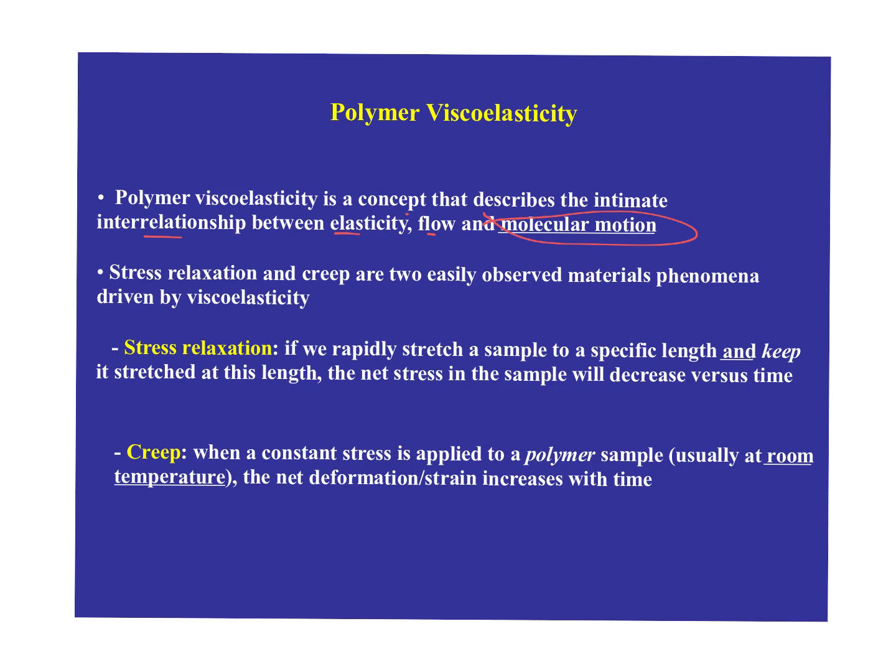So PVC at 250 degrees is going to have a higher viscosity than polyethylene at 250 degrees, or pretty much any temperature for that matter, because of that secondary bonding. Secondary bonding doesn't go away just because we heat the polymer up. It's still active, it's still important, it's still part of what determines how it resists the process of shearing.